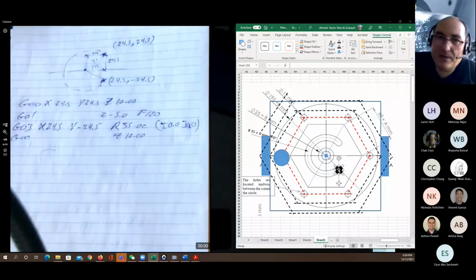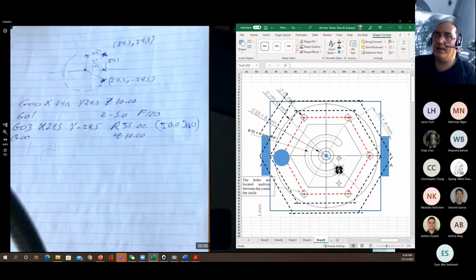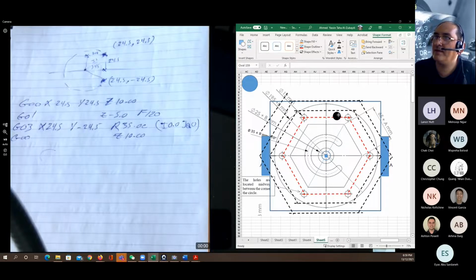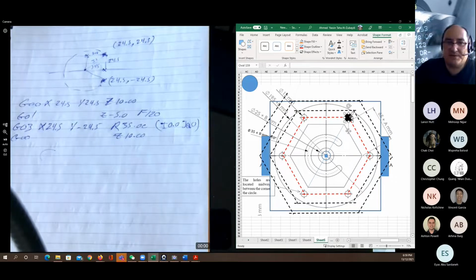Okay, now anyone have an idea on how to drill these small holes? You just move over the top of them with G00 and then to the final depth, which is -15, and then go up. You go to the next location, G01 to the -15 Z, and you go up. And you keep doing that for all the 6 points.